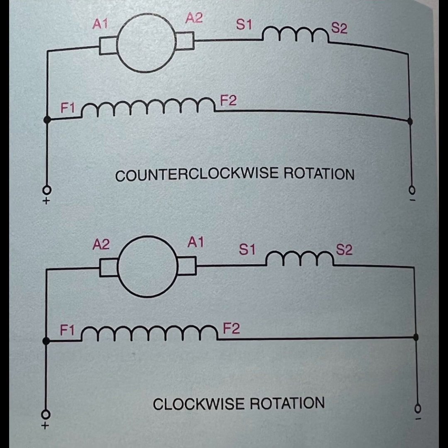Standard connections. When DC motors are wound, terminal leads are marked in a standard manner. This allows the directional rotation to be determined when the motor windings are connected. The direction of rotation is determined by facing the commutator end of the DC motor, which is generally located on the rear of the motor, but not always.